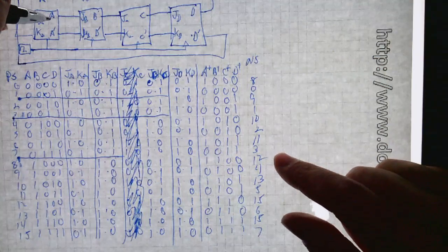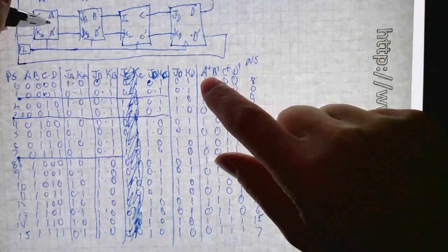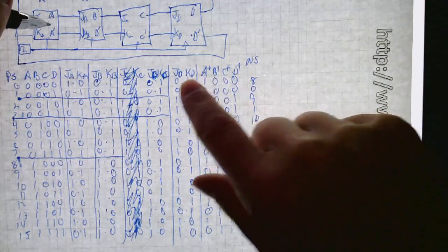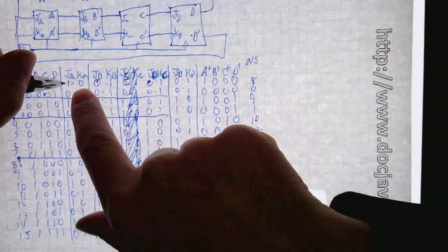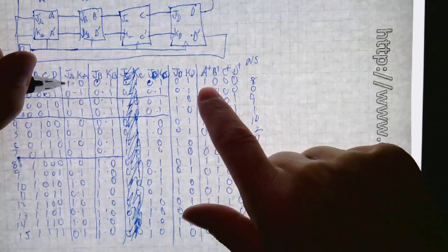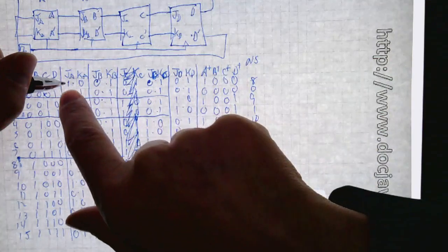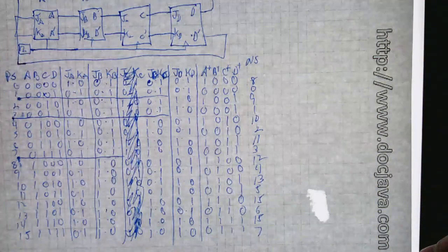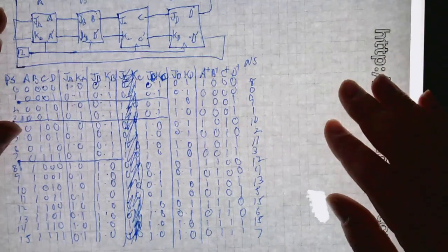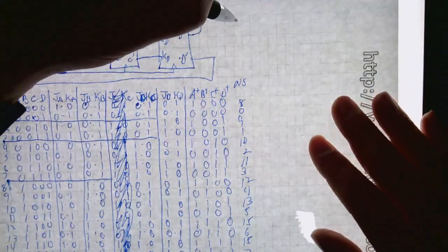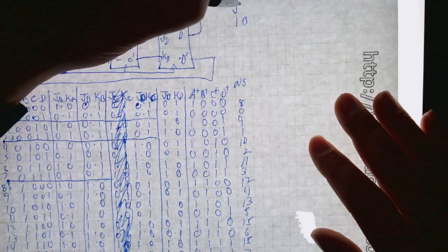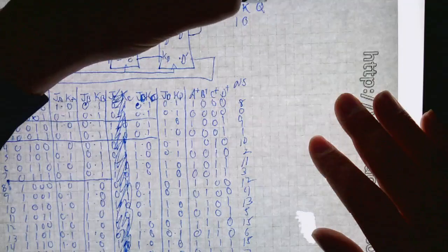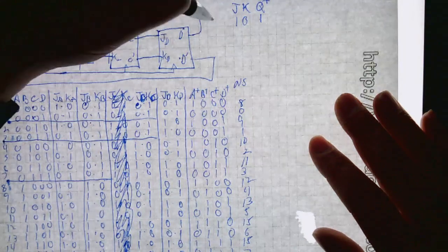Yeah, so A plus is the next state for A if the input for A is 1, 0. In other words, because 1, 0 is being used on input, the next state for A will be a set state, because this says set and don't reset. If we remember correctly, if you put in 1, 0 for J and K, the next state, Q plus, is going to be 1, because that says set.